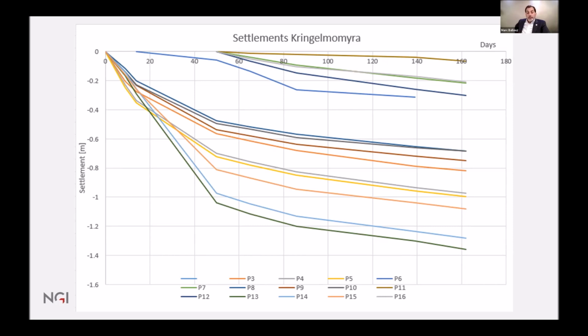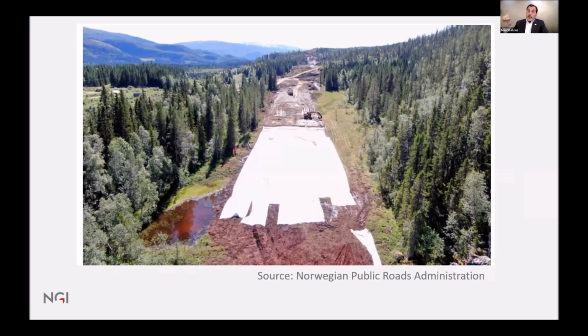I had once a contractor do this without stabilization, without the geotextile, and he would keep adding loads and backfilling. We come back the next day and the whole berm or embankment would settle and disappear. In the jungle, I'm telling the story for everyone and the audience. You could hear the trees cracking and falling 40 meters away.